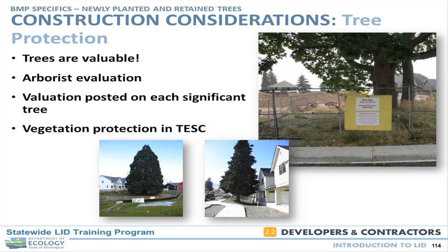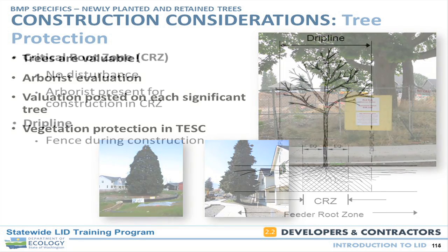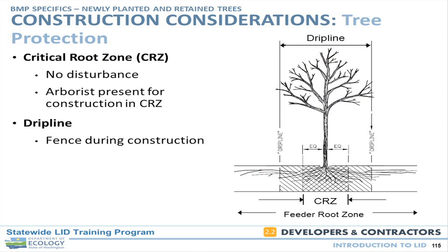And then obviously vegetation protection as a valuable part of the erosion and sediment control. So the critical root zone is the key part, not just putting protection fencing around the trunks and calling it good. Depending on the type of tree, and this is where the arborist direction gives you some clear guidance, there are certain species where you go even up to a third or a half past the drip line of the tree. So that starts to be some significant areas, and that's looking at that as a no construction activity within that zone and being very clear that that goes into the plans.